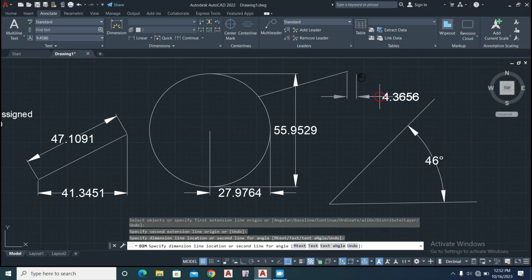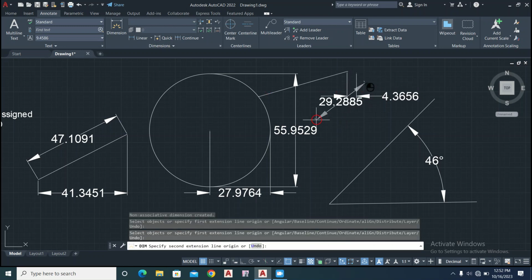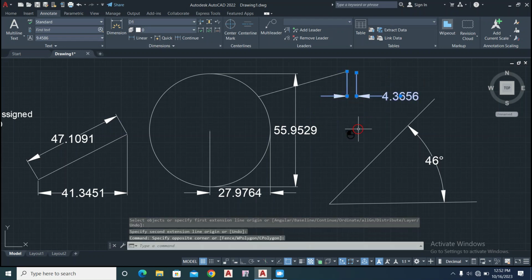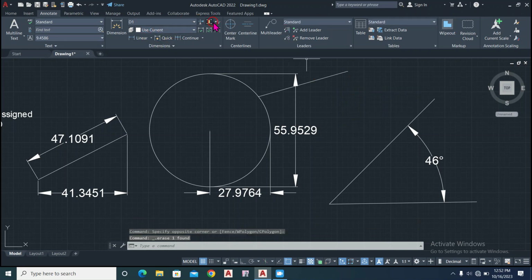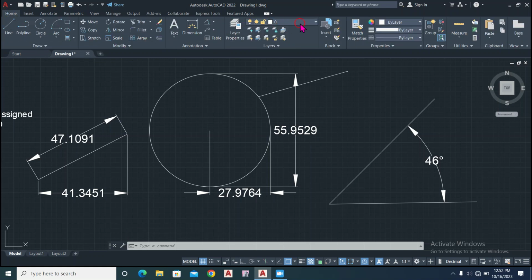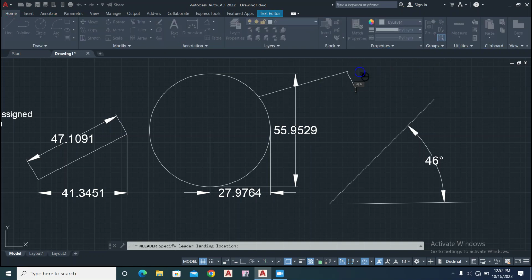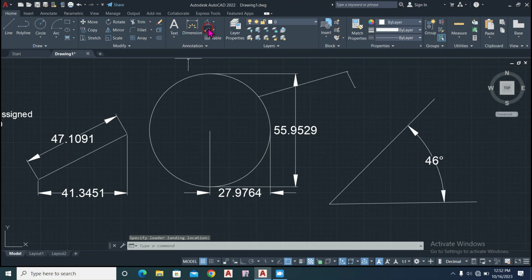So here you can see the dimension, so through this d1 we have to apply the dimensions to the leader. So you can also change the dimension for this leader line. And so now we proceed to the next. Through leader you can assign how much is the dia or any other line specifically by an arrow.